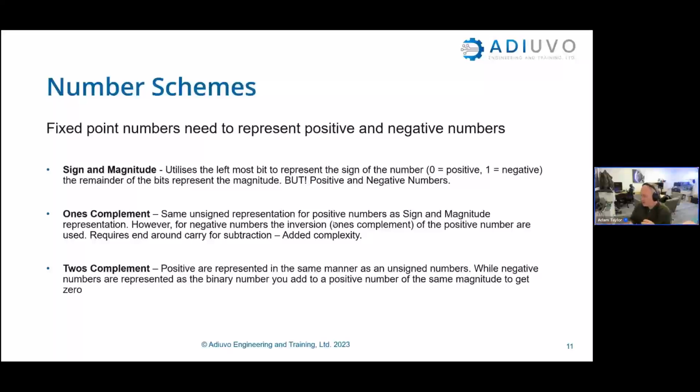So Sam, I'll come to your question in a second. It doesn't actually need way more resources than a floating point one would. Typically, floating point uses more. I don't have a direct example of this, but I will create a blog using some of the libraries I'm going to show you in a little while, and I'll do a comparison between fixed point and floating point, and I'll throw that in a few different FPGAs as well. So I'll do it in an Artix, an UltraScale, and then I'll throw it in a Versal as well, so we can see what impact comes when it maps to a DSP, maps to DSP58.